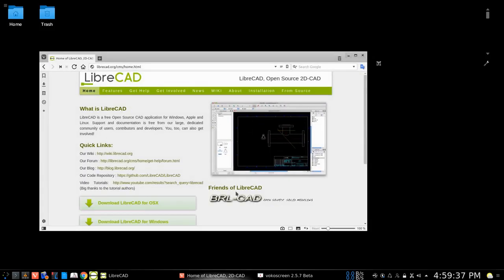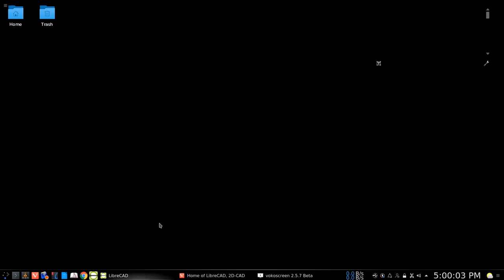Okay, welcome to another howtopam LibreCad tutorial. We already looked at creating a title block, and we can actually save that as a block or as a drawing template. So first, we're going to save as a template and then show you how to turn it into a block.